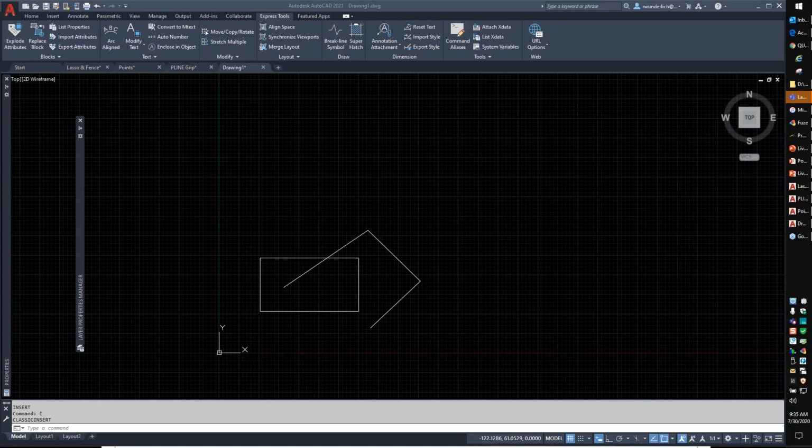Can you speak real quick on the dangers of copy and paste or drag and drop data into your drawings? Yes, Kelly, I can. The biggest concern I have when you copy and paste from other drawings or you drag and drop data from other drawings into your current drawing is you don't know if the other drawing has issues. I covered part of this in, I think it was my January webinar, where I talked about how to keep drawings clean with the minus purge, reg apps, things like that.